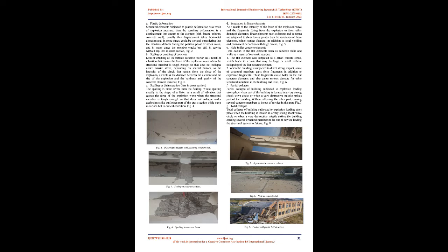B. Scaling or crushing of concrete. Loss or crushing of the surface concrete mortar, as a result of vibration caused by the force of the explosion wave, when the structural member is tough enough that it does not collapse under missile strike. It depends on several factors, such as the intensity of the shock that results from the force of the explosion, the distance between the element and the site of the explosion, and the hardness and quality of the concrete element material.